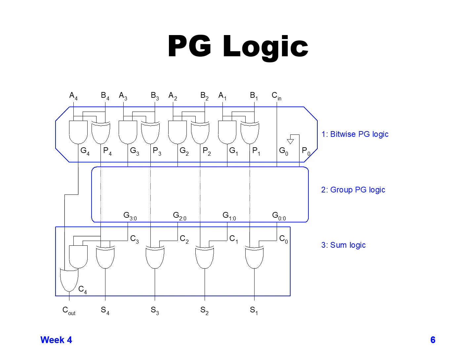For any given bit, based on the logic that we were talking about in the previous foil, we can calculate propagate 1 and generate 1 for the first bit just based on the A and B values, so A sub 1 and B sub 1. A XORed with B gives us our propagate 1, and A ANDed with B gives us our generate 1. And likewise, you can do that for each of the 4 bits.